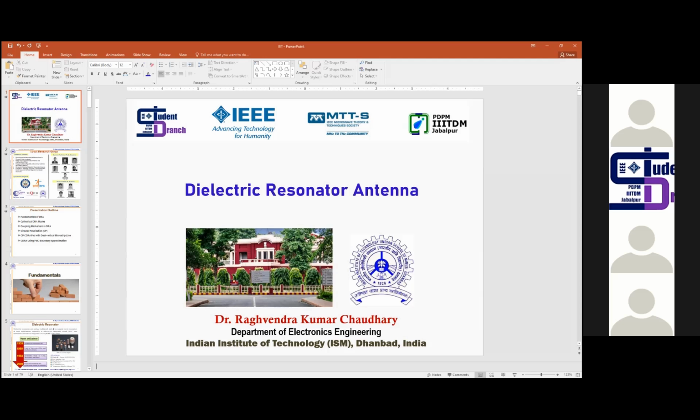But if you want to calculate the resonance frequency, that time you have to use the boundary condition that you said. Okay, for the resonant frequency, only the bottom x equal to 0 will be a PEC, and all the walls are PMC, sir. It depends on what environment we are using, because all the analysis and other things happened with the suspended DR. So if we are changing the boundary conditions, surely things will change. You have to keep this in your mind.